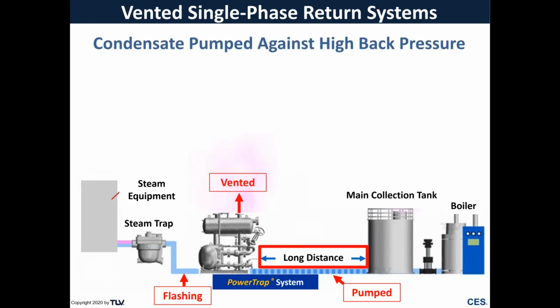And here, basically, we're needing some type of pump to move that condensate over long distances or over high lifts. Basically, we can't just rely upon the steam trap to return that condensate all the way back to the point of collection.